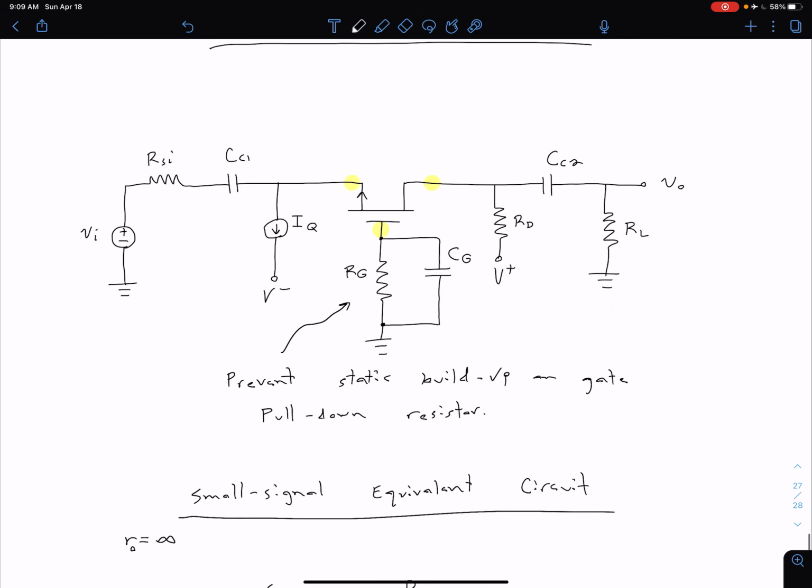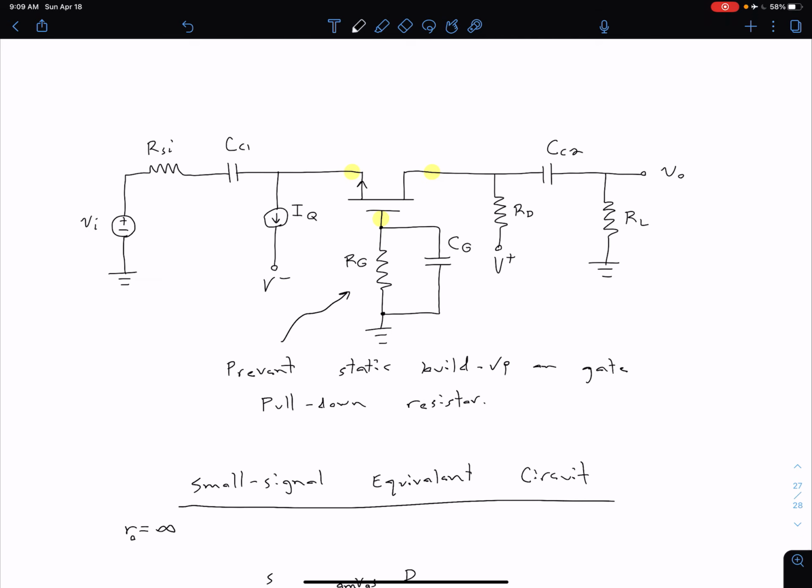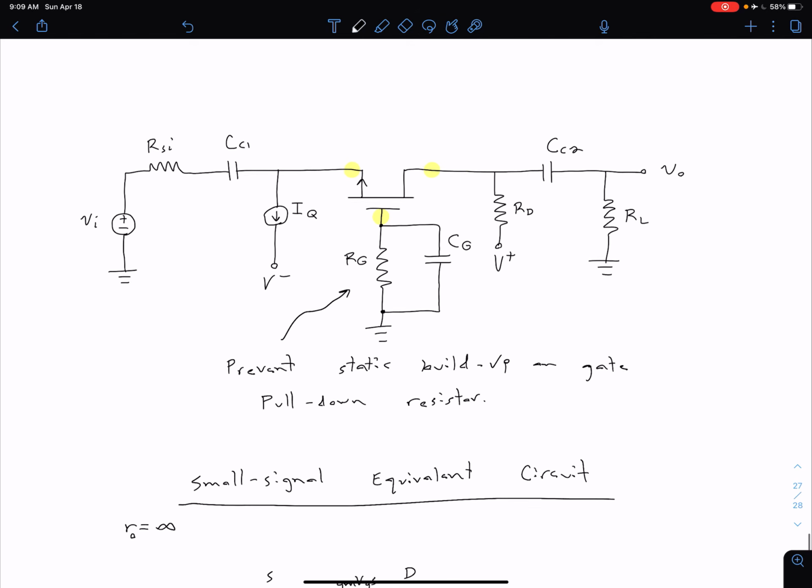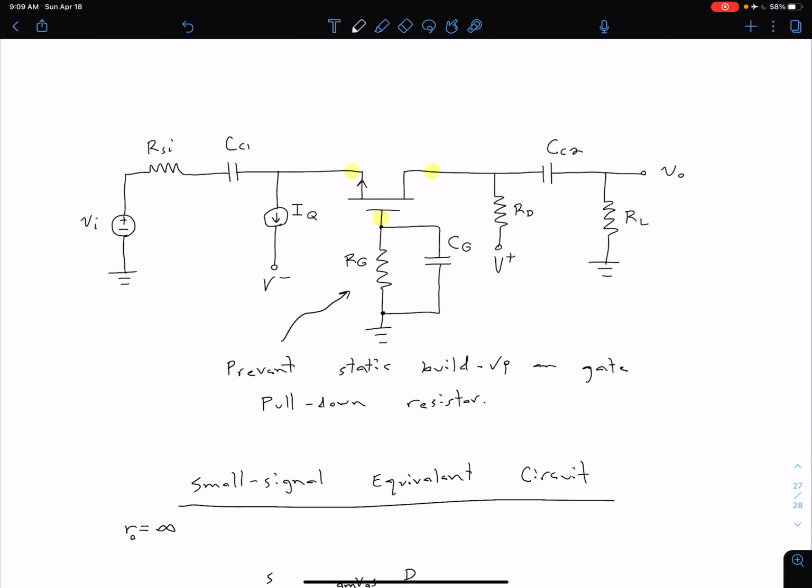Okay, coming back up here, we now have this current source, and again, we're deactivating DC sources. For a current source, if we want zero current, we open the current source. That's just going to be an open circuit here, so we're not going to have any path to ground from our source, but we are going to have a short circuit through this capacitor, and then we can go through RSI and VI to ground.